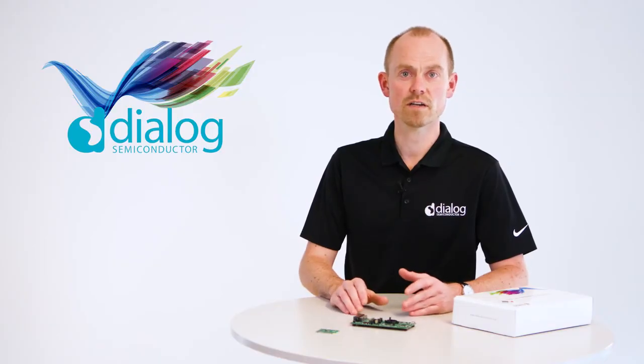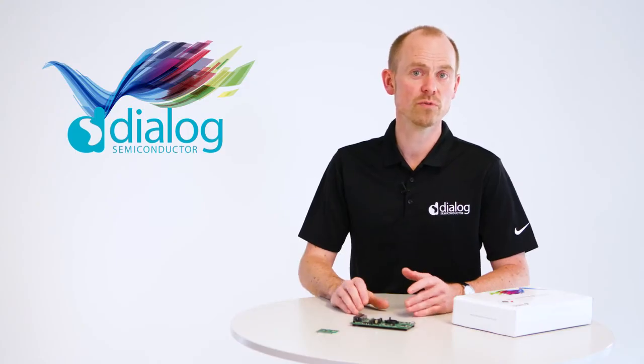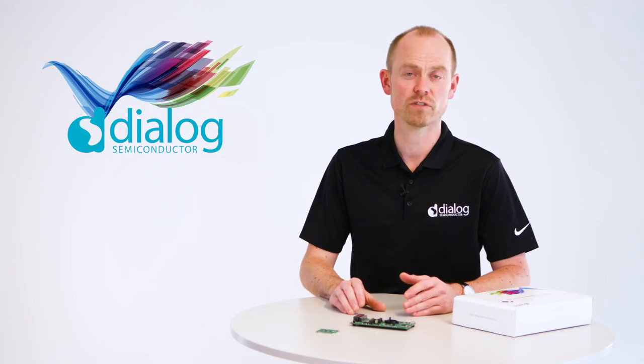As I mentioned at the start of this video, I want to go into a little bit more detail on the power profiling and the current measurement circuits on the motherboard. Using the SmartSnippets power profiling tool, we can visualize in real time the current consumption of the DA14585. We'll continue with this barebone project to demonstrate this feature.